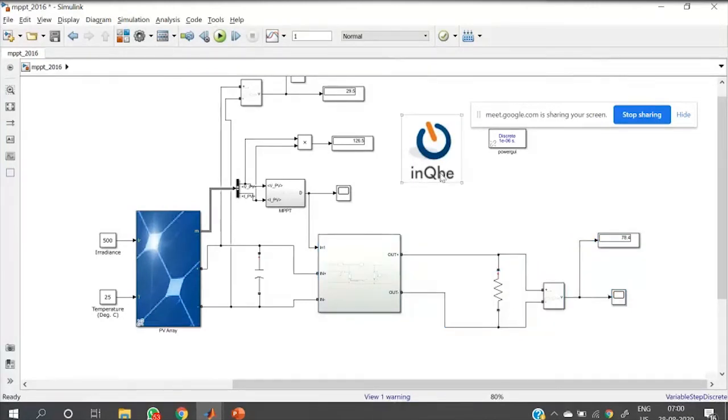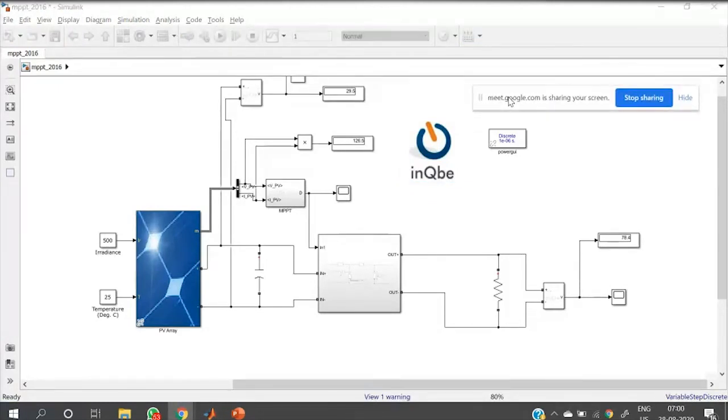Here we change the duty cycle to get maximum power; in my application, I changed the frequency of the pump to change the motor speed to get maximum power. That means whatever parameter can vary the load power can be used to find the MPPT point. That means load variation should come into the picture.